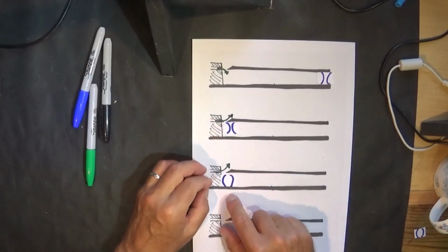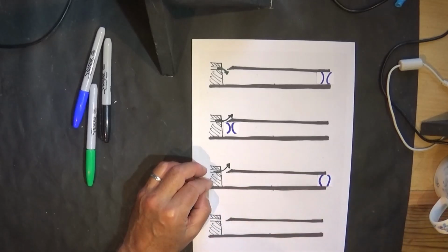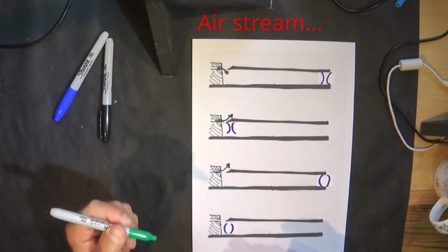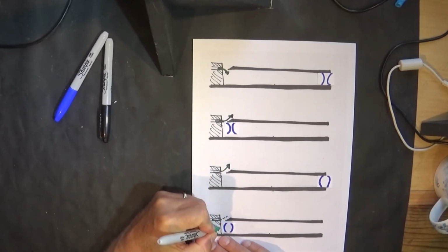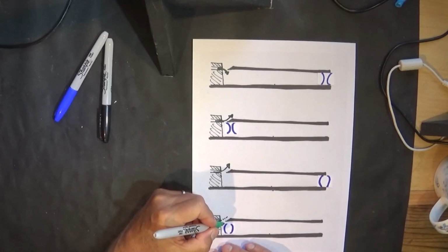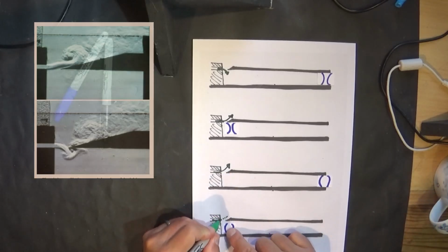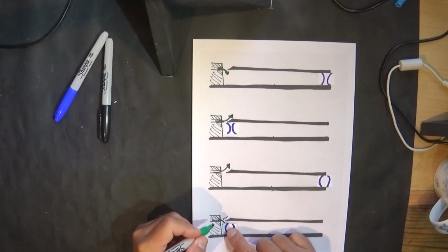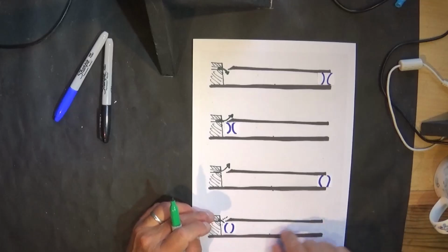It will pull the air out, which again will go down to the end, be reflected from the end, and come back, by which time our wave going out will be unstable, and you can see in the pictures they've taken there it's very turbulent and unstable, and will be sucked back in again, and we will have another pressure wave going down.